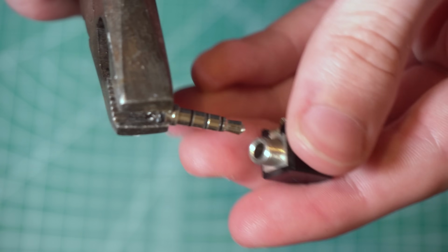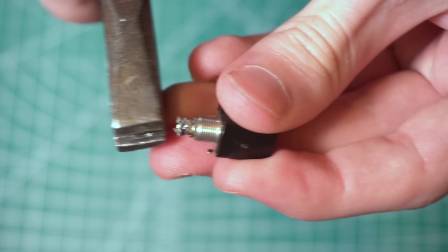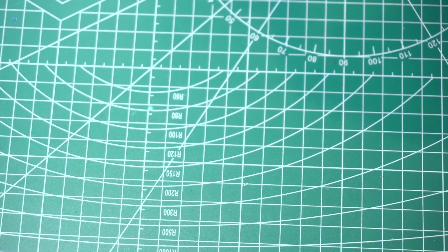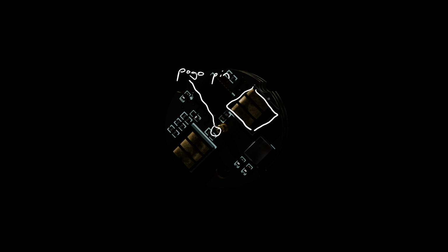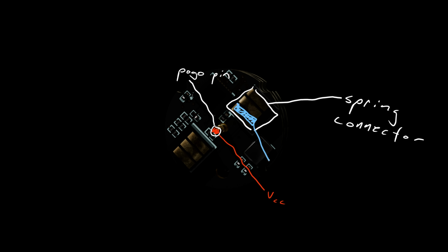If the connector itself fails by breaking, it does so not safely. Those of you who have had a headphone connector break off inside a device would know, it is difficult to remove or replace. So instead of making our connector have pads around a cylinder, we can flatten them, creating a circular connector. This way, all of the connections happen at the surface, and the connector can freely rotate. The cable side will just be a flat PCB for simplicity, and the device itself will have a spring connector connecting to each of the pads, with a single pogo pin for power in the center.